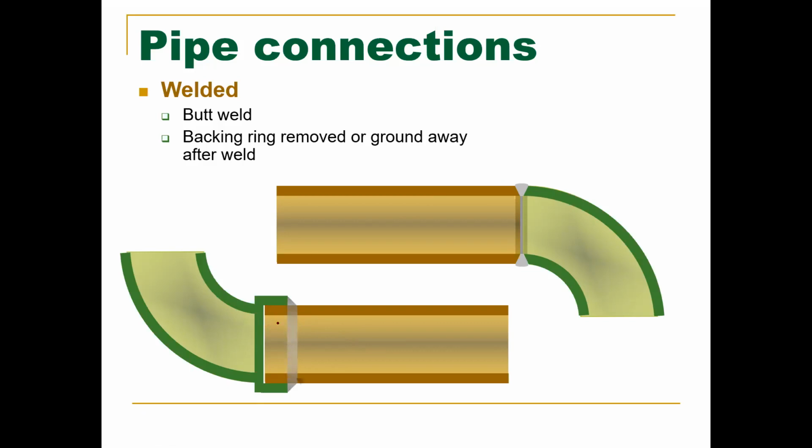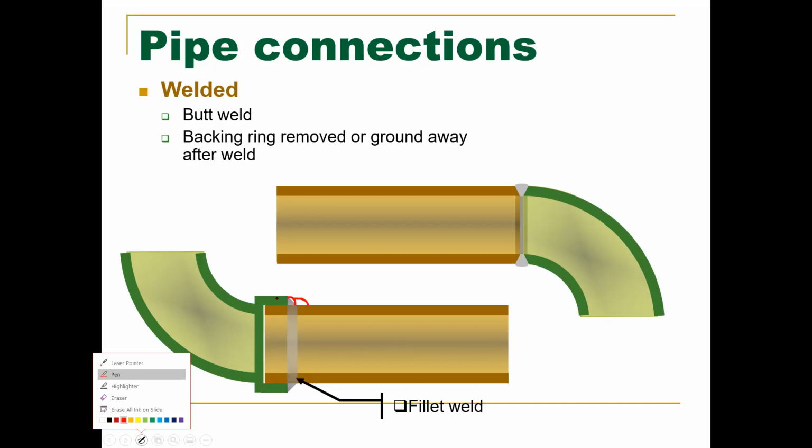All right. So when you weld here, it's called a fillet weld. Normally, when you do this, it's not just going to be one weld. So you're going to weld here. That's going to be my bead right there. And then you usually do 2 more on top of that. I drew that too big. It usually goes like this. So you'd stick 1 in there, and then 1 here, and then 1 here. All right, 3 passes or so, depending on how big it is. It usually gives a stronger weld if you do it that way.